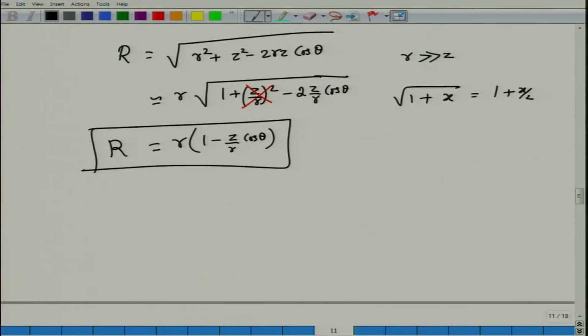Why should you keep this in mind? Because if I go back to the vector potential and write it as a function of r and theta, it will be mu by 4 pi times the integral, of course along the z axis. So, you have the current element I0 of z e power j psi of z, which again you do not know, and in the denominator you have e power minus j k r.